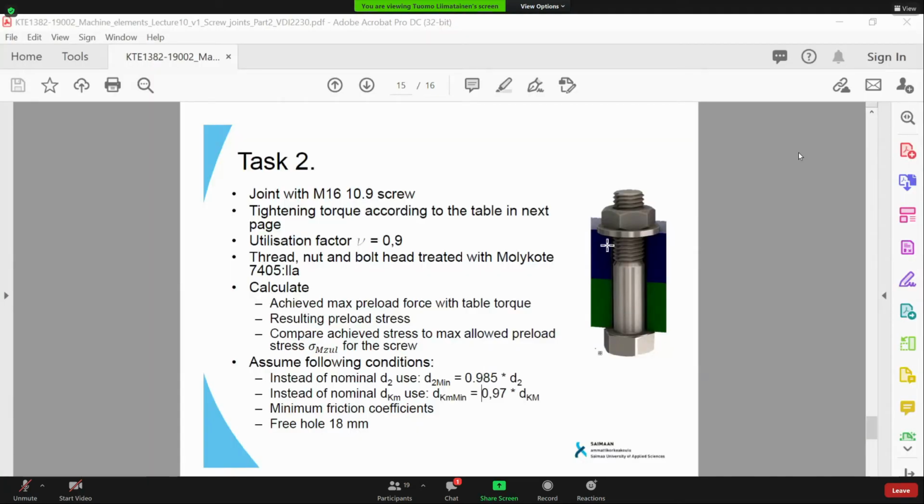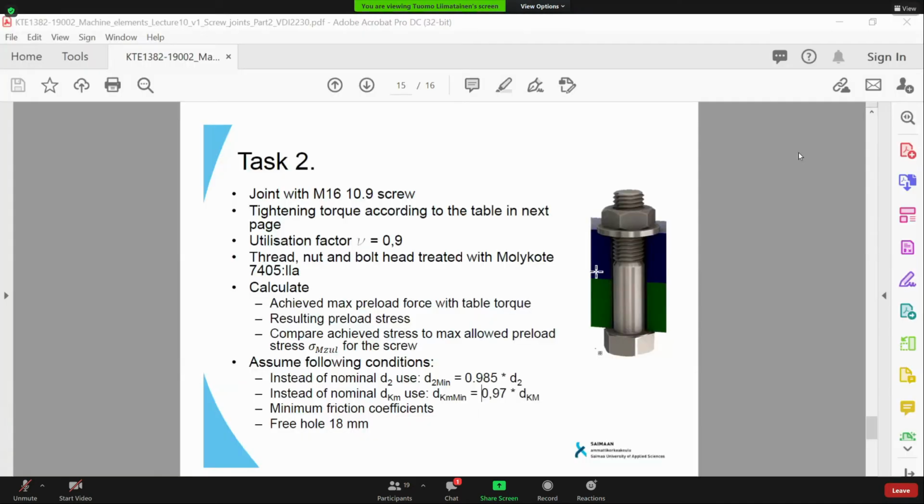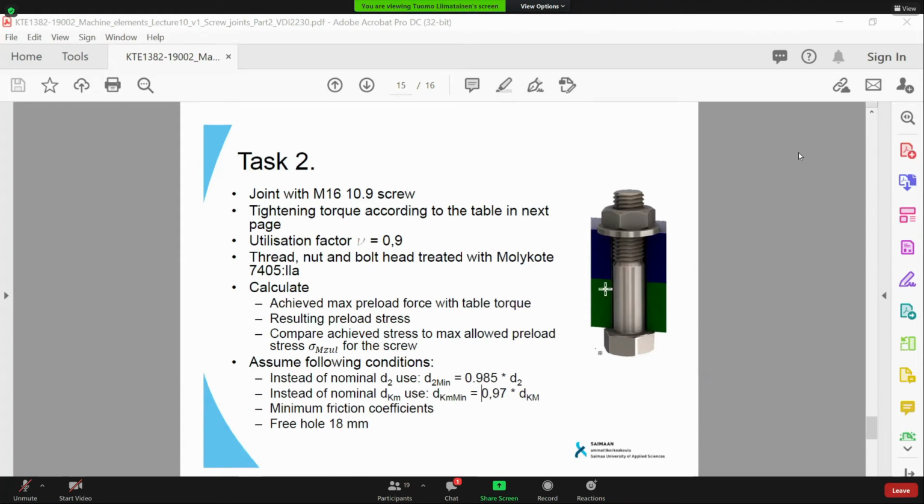And therefore, as we last time, I think, checked the video on how to use this tension tool, where we can just pull the screw and obtain the final preloading force. That is by far a much more accurate method of obtaining a preloading force. But of course, it's quite slow and toilsome to use. If you have, for example, 150 bolts of small size, it's quite an impossible task to tighten them with this kind of tensioning tool.